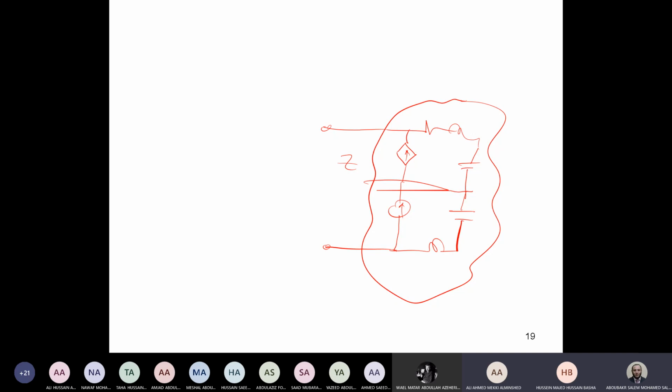Thevenin, yes, we use it. How can we get Thevenin, guys, for this machine? We have a machine now with many elements here, and we would just like to get the relation or the impedance of this network. How can we get it? Put a test voltage. Put a voltage source, a test voltage, and then find the resistance seen by the voltage source. Then measure the current. If we can find the current, we can find the resistance.